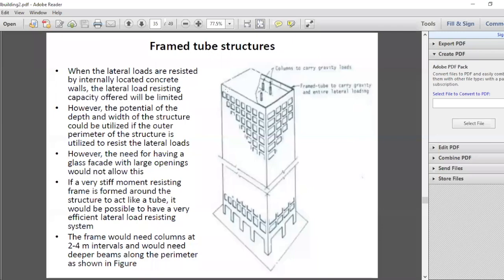That means when you have a beam acting with the slab, we can say that the full flange width is effective from one center to the other. But in actual practice, what you find is that width is not effective. It is less. And the reason is plane sections do not remain plane in the flanges when the distance between the end of the flange and the web is high. And this is called the shear lag effect.